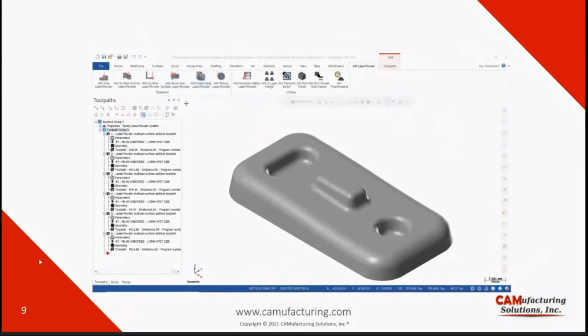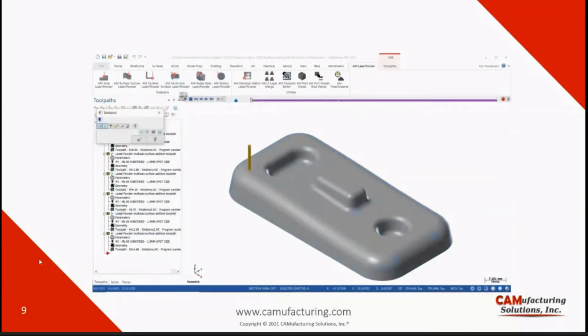So we have 6 different AM multi-axis toolpaths for 6 different surfaces of this part. Surface 1, 2, 3, 4, 5, and 6. So you can have 2 different strategies while using multi-axis surface. One of them is a raster pattern. So you will have a raster pattern coated on your surface. It's a very good option for flat surfaces, as you can see on surface number 1.